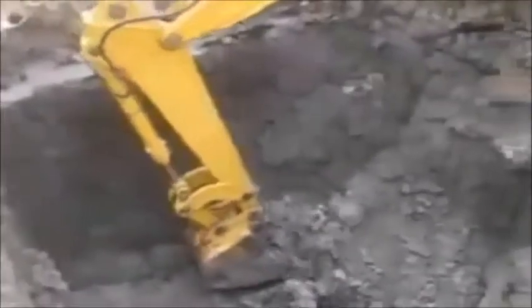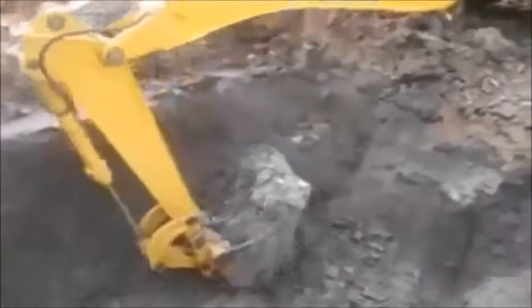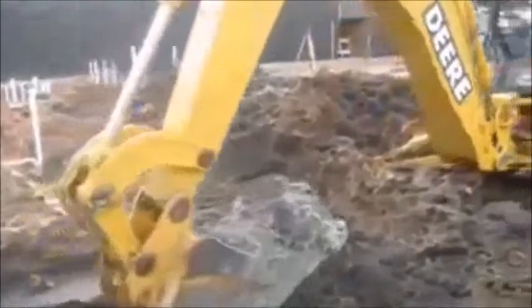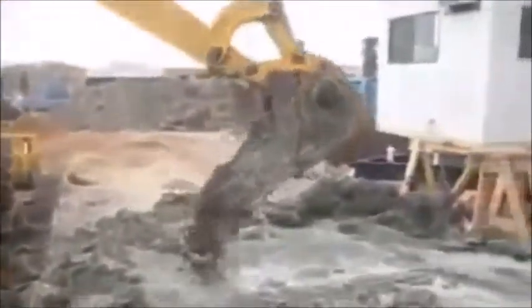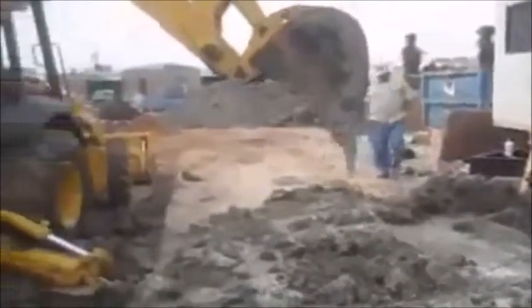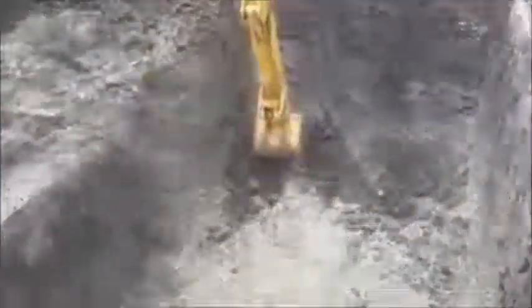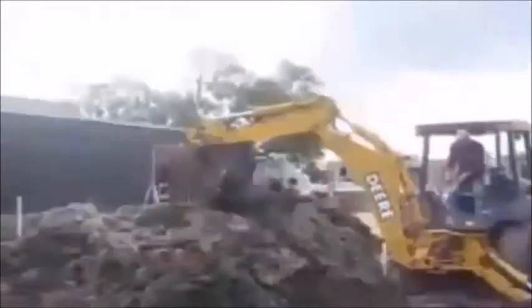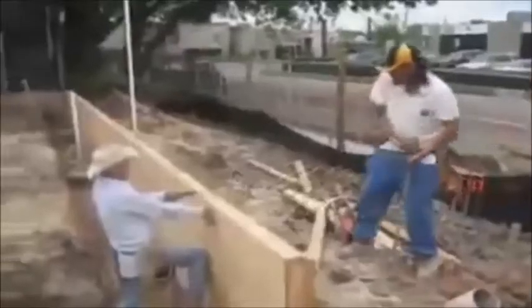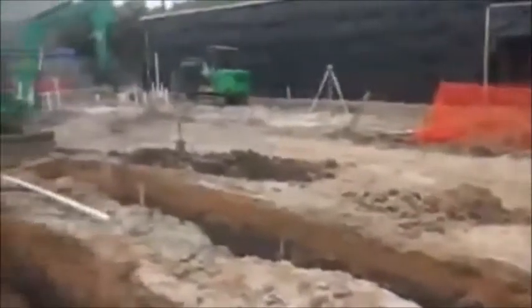Now, let us look at the video that mainly shows the process of constructing a ground beam. First, the construction starts with excavation. Next will be the construction of formwork. The formwork is constructed using sawn formwork at the side of the ground beam. Then, the steel bar, girths and stirrups will be placed neatly into the formwork.